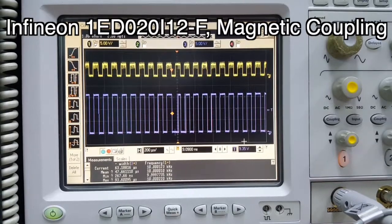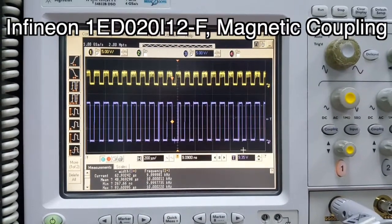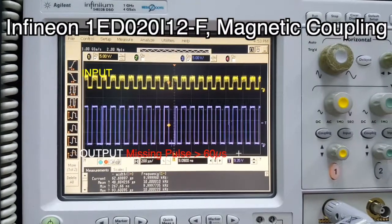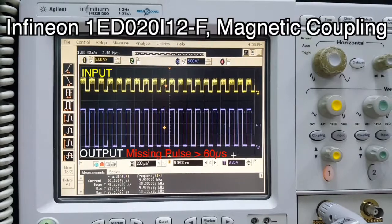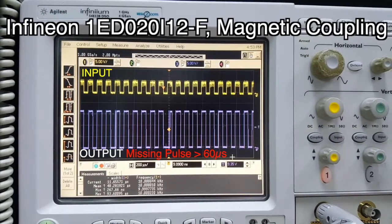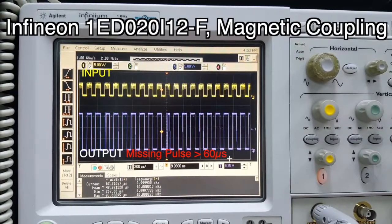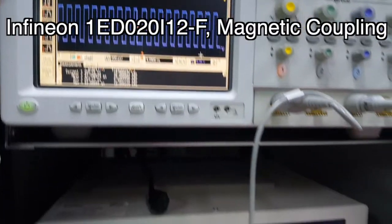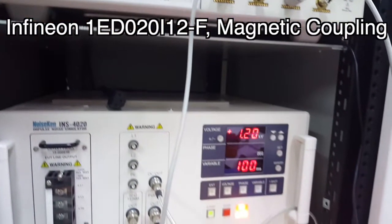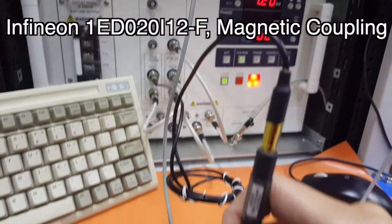Next, we're going to test Infineon's 1ED020I12-F, one of the EiceDRIVER family, which uses coreless transformers to provide isolated communication across the galvanic isolation. The device uses an IGBT desaturation protection with a fault status output. The Infineon gate driver has missing output pulses when 1200 volts periodic impulse noise is introduced on the surface of the gate driver's package.